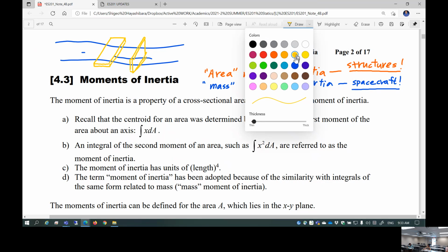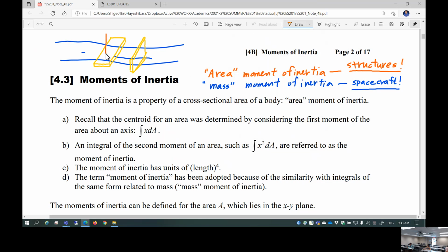Suppose you apply the force right here and right here. This force is trying to bend this material, so especially in the center of this material, you have a maximum bending moment applied. Of course, you can draw a shear moment diagram for this, which is kind of simple. You realize this is the maximum moment developed in the center, and obviously this orientation is much stronger, more resistive against that bending moment. Why is that? It's the same wood; you just rotate the direction.